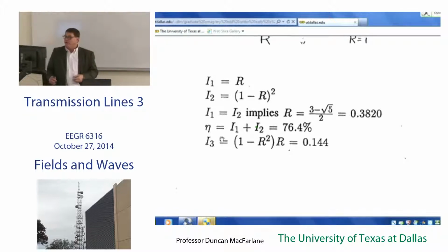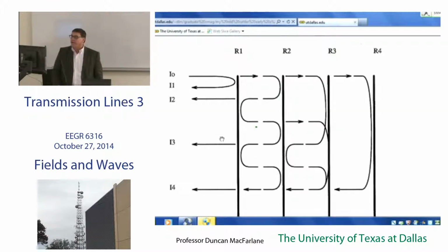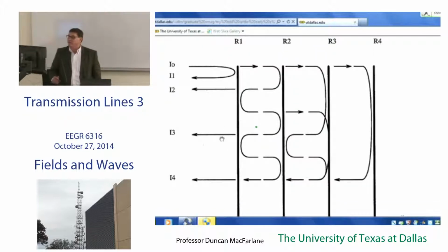Okay, and that's actually a useful device. I can continue on this path. Okay, I can continue to add mirrors together. And this might be transmission line 1 at 50 ohms, plus another one at 60 ohms, plus another one at 50 ohms, and so on down the line, so that I've got multiple reflections of these short, sharp pulses between the two.